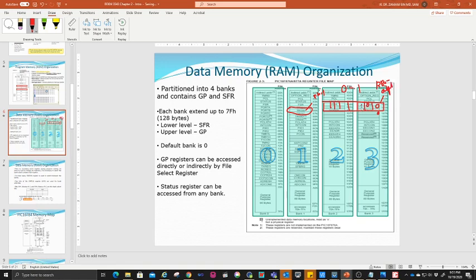If you put all 0, it means that you are setting up port B pin 0 to pin 7 all as output. If you change this 0 to 1, for example here you put all 1, which means that you are going to change this port from pin 0 to pin 7 all as digital input.